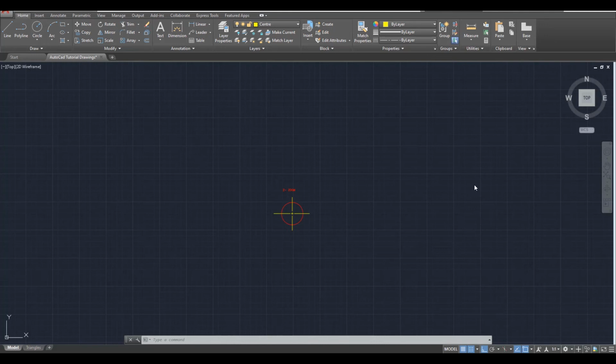So as we said, Z now is for the zoom tool, and just imagine this scenario. You're in CAD and you're looking at a drawing and you want to actually see it magnified. How would you do that? Rather easily, you can use the Z tool. So you hit Z on the command line, enter, and you then specify where or how you want the zoom to actually be done. So you can actually zoom to scale.